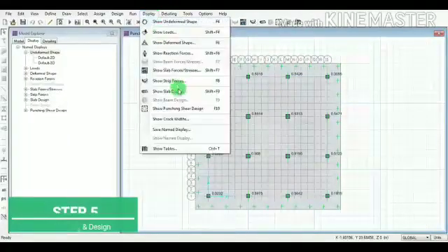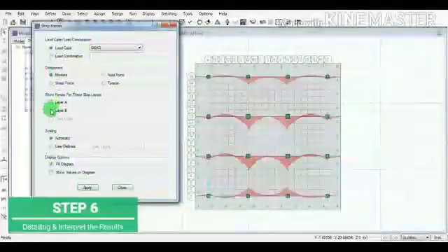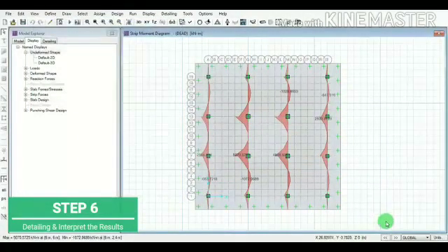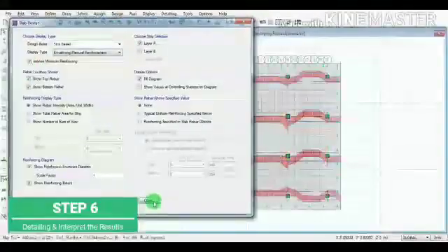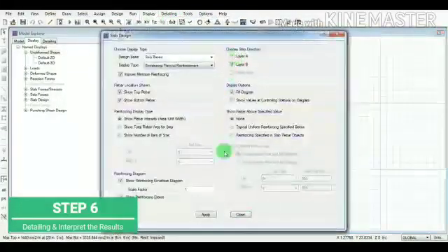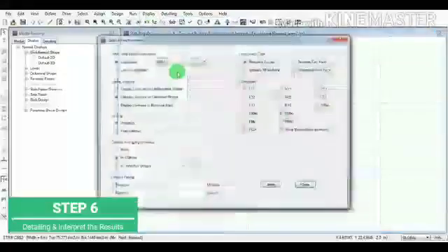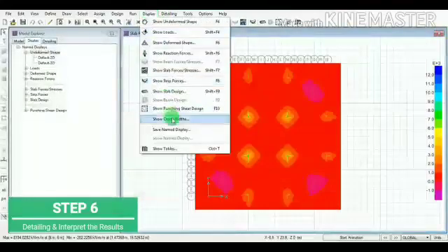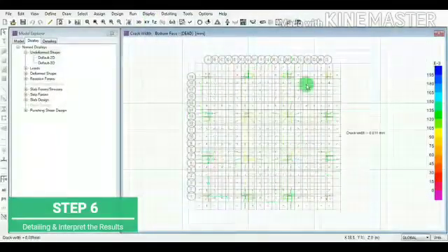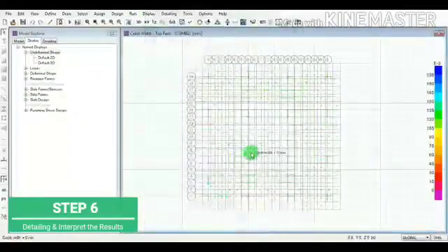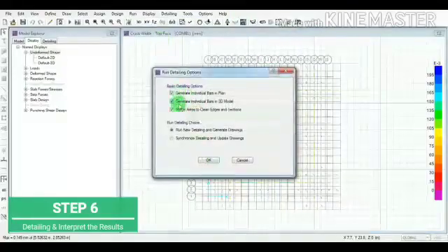Now the next part is to view the different load combinations in detail. Before that, the strip forces in layer A and B. Now get the required reinforcement. Now similarly in layer B for load combination A. This is the crack width values for the slab top and slab bottom. These are minor cracks. Then start the detailing option.